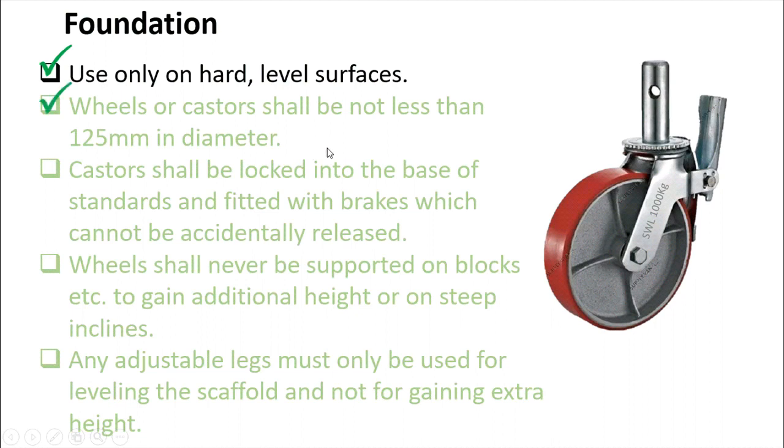Okay, so when you are using the mobile scaffold, you need to check the area is level, the surface is level and hard, fully compacted, to prevent the wheels sinking on the surface, because once it's sinking, the scaffolding will collapse or may tip over on the ground, so the stability is compromised.